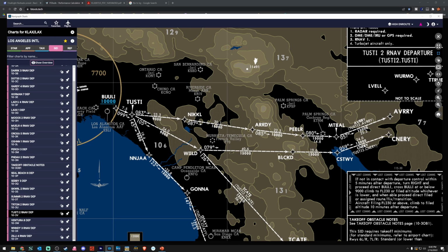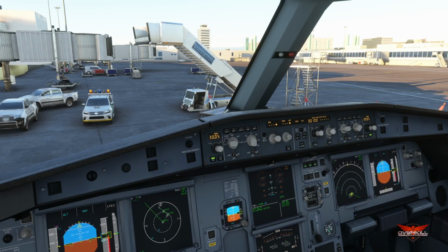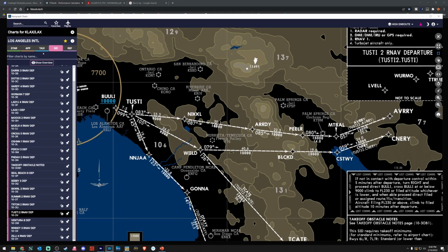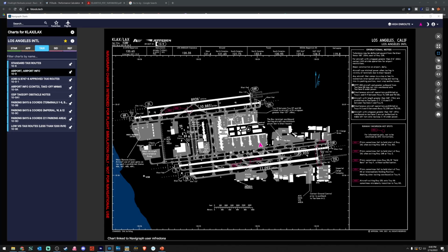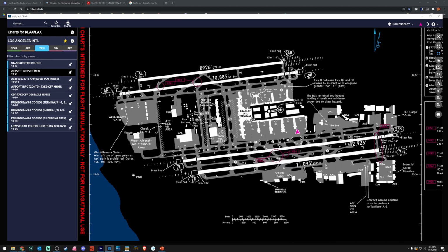All right. Turning off the display this time. We're going to set our initial takeoff target for altitude 15,000. There we go. Heading will be sure to match up as we take off. However, if you wanted to set that up now, which we can do, we'll go to our taxi information, go to airport information so we can see the chart. And we're going to come down here. This is as far as I can zoom this in, guys, but it actually says 07 left here, and the final runway heading is 071 degrees.